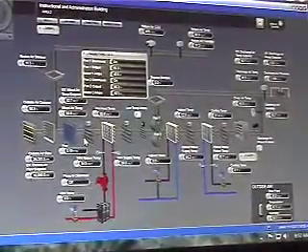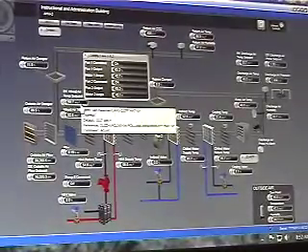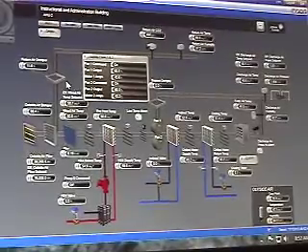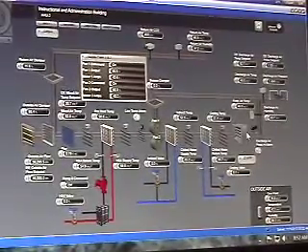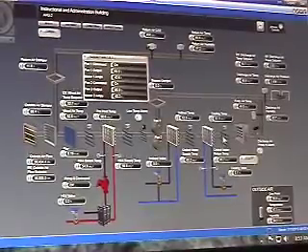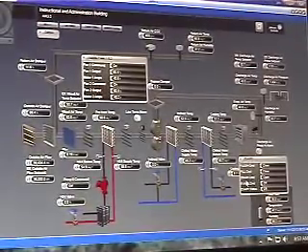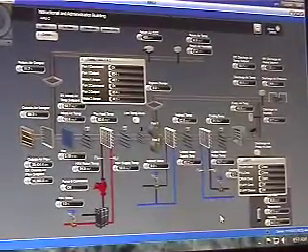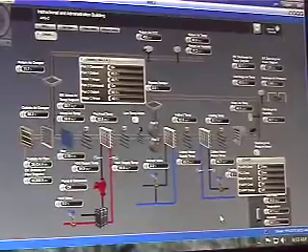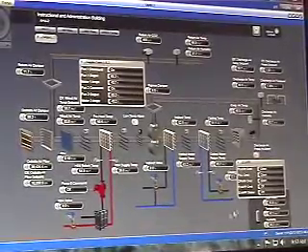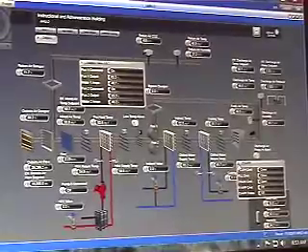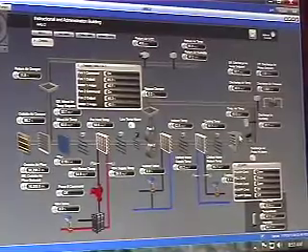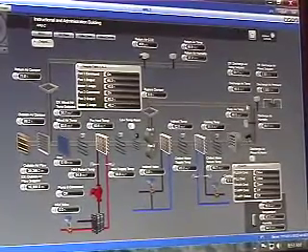When the outside air temperature gets above whatever that floating set point is, we will then switch to, depending on if it's available, state 3, which would be your evap media. The first thing we do is shut the drain valve, open up the fill command, and leave the flush command closed. That'll run that way for about 15 minutes while we fill the pan up. After that, the evap pump will turn on. We've got a status on, and now we're making these dampers 100% open, air's coming through, and we're now wetting the pads and blowing that cold air through the evaporative media.